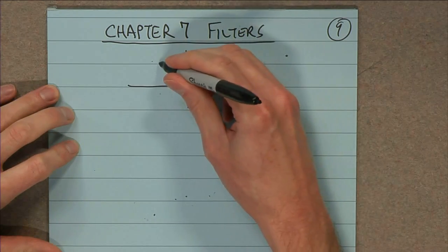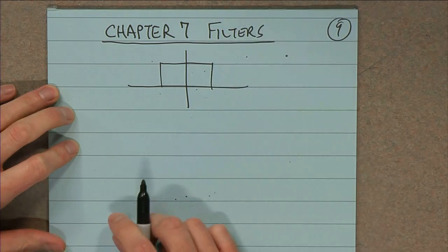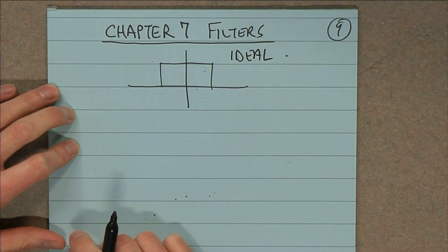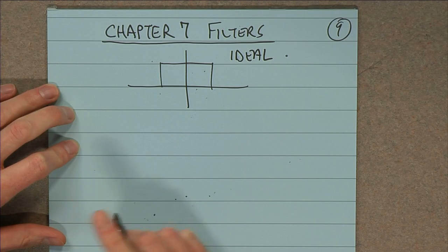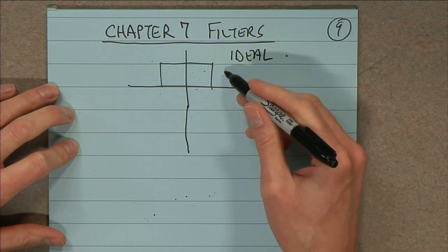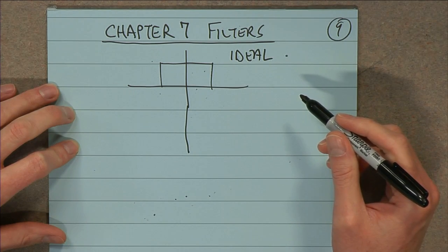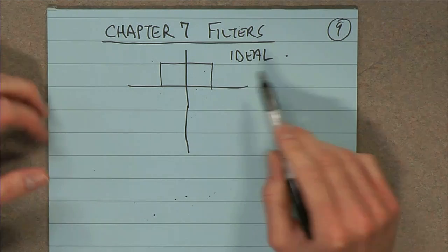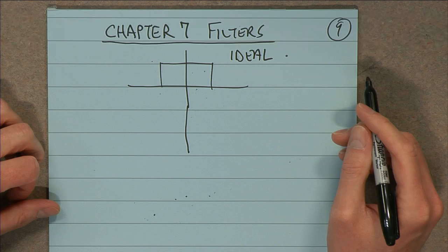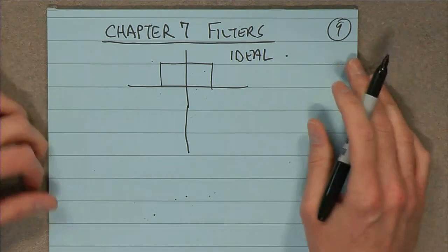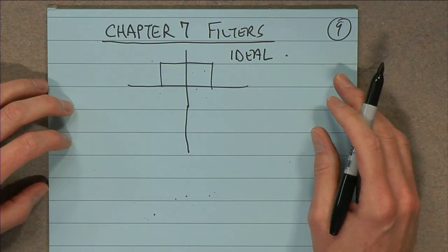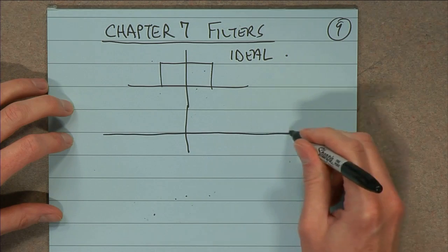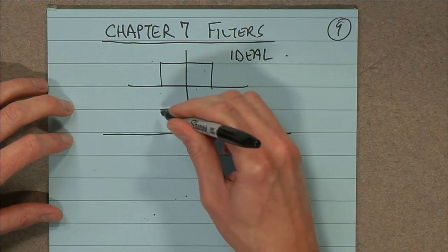At the beginning of the course, we were just talking about concepts. We use this ideal filter concept all the time. Well, nothing looks like that. In fact, I think we derived, if you just integrate this up and try to get a time response for a filter like this, it's not even causal unless you add the right phase to it. So there's some non-real world effects there.